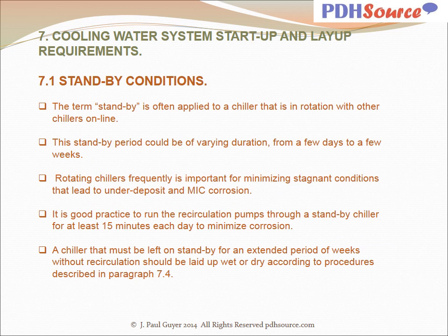The term standby is often applied to a chiller that is in rotation with other chillers online. This standby period could be of varying duration from a few days to a few weeks. Rotating chillers frequently is important for minimizing stagnant conditions that lead to underdeposit and MIC corrosion. It's good practice to run the recirculation pumps through a standby chiller for at least 15 minutes each day to minimize corrosion. A chiller that must be left on standby for an extended period of weeks without recirculation should be laid up wet or dry according to procedures described.